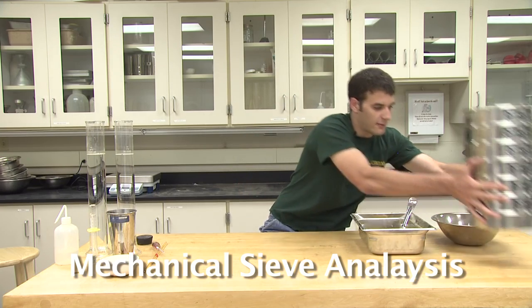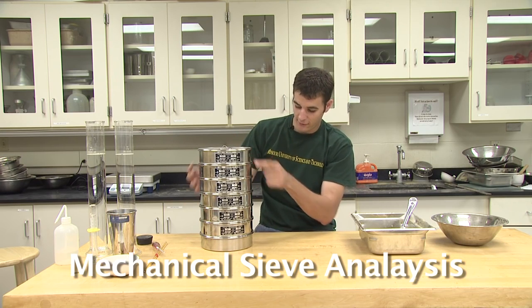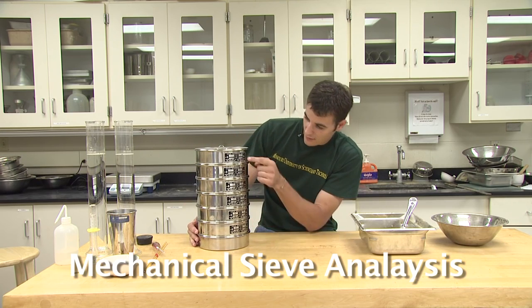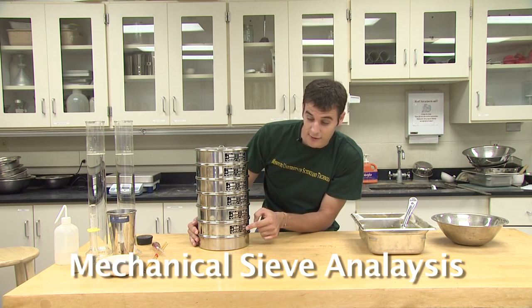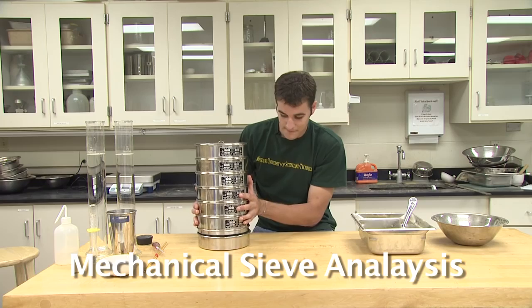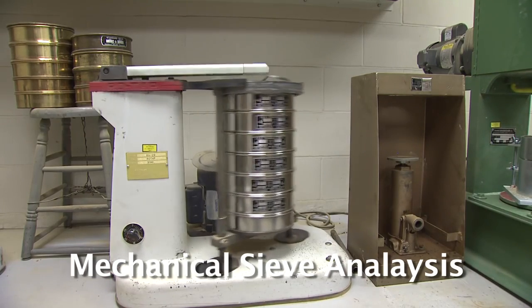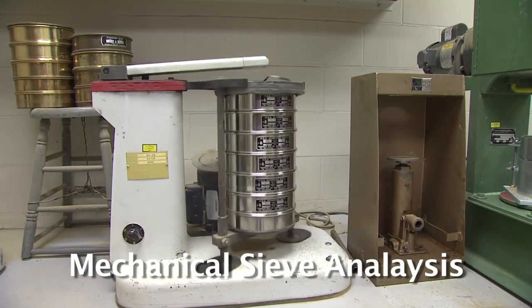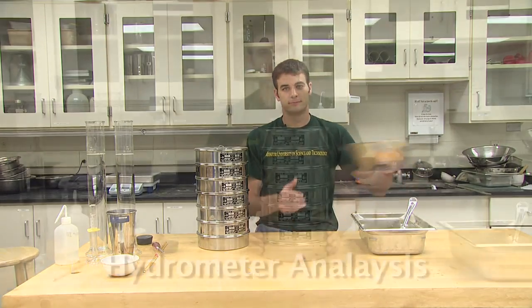The devices required in order to conduct a mechanical sieve analysis are a stack of sieves ranging from number 4 to number 200: 4, 10, 20, 40, 100, 200, the pan, and a lid, a mechanical shaker, a digital balance, and a weighing bowl.